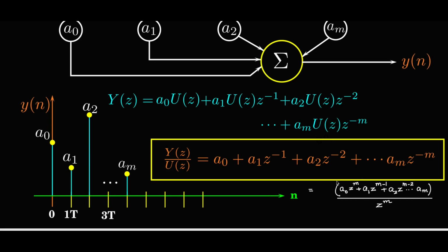Only the zeros lie at distinct places on the z plane. So if you have m delay elements, you will have zero 1, zero 2 up to zero m, and you have the potential to design the positioning of the zeros. You have the ability to place the zeros appropriately to obtain FIR characteristics.